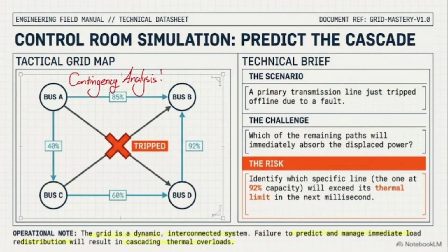So when we are talking about this kind of aspect, obviously we cannot accept this amount of problem, or this huge cost of time and money, just based on our guesses, right? As you remember, I told you that one of the jobs of the transmission planners is to simulate this problem. How can we simulate it? By simulating the actual grid in software, like PSCAD and PSSE, and putting your system under intentional pressure. It means that we give the system some faults and we see what would happen.